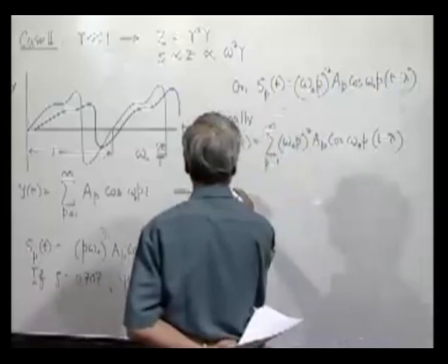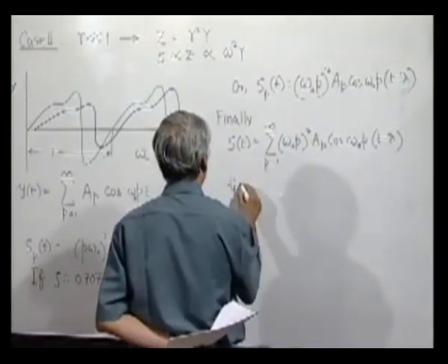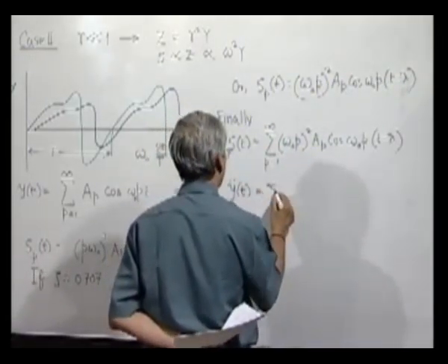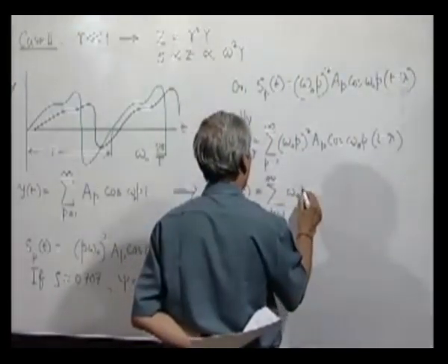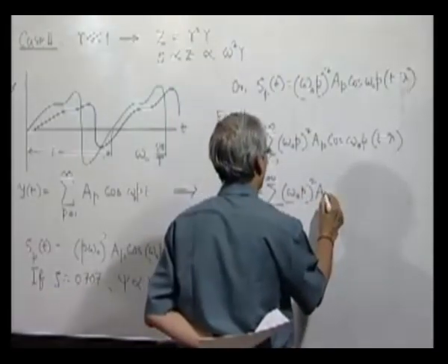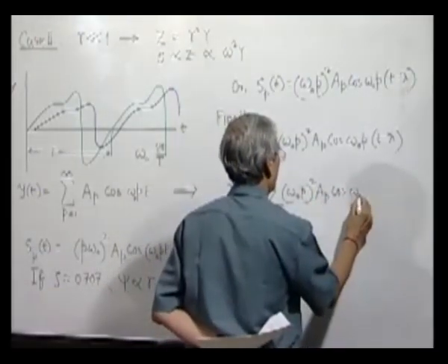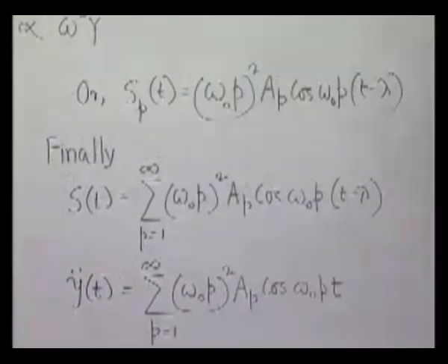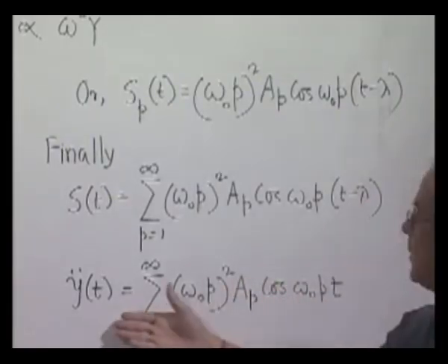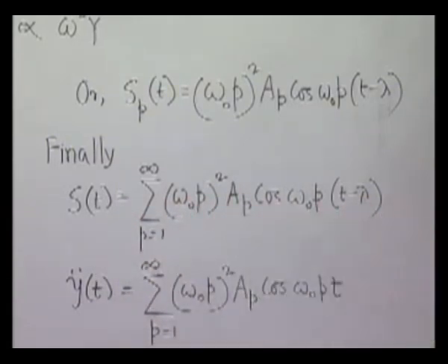Double derivative of this, that is Y double dot p, the acceleration is, so comparing these two, we find that even if the vibration is not harmonic but periodic, the acceleration pattern and the voltage generated, those patterns are the same, only there is a slight shift in the origin of t, that is all, but the shape is undistorted.